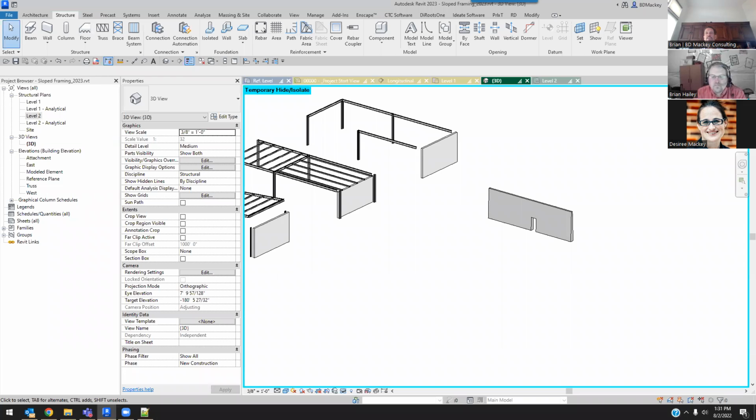Yeah, the only other thought I was going to say is what happens if you take that CAD file into a blank file? Are you going to get something else? Or what if you try removing the CAD file and bringing it back in? I know that completely sucks because of all the settings, but sometimes just getting rid of the CAD file and bringing it back in, Revit's got to rethink about it. And I've seen that fix it as well. So not sure what the deal is, but yeah. So hopefully that makes sense for you.